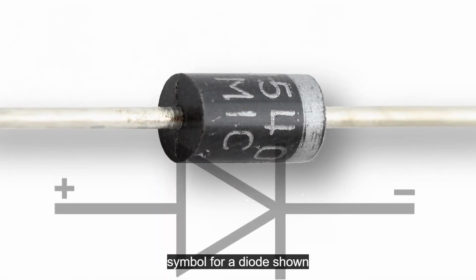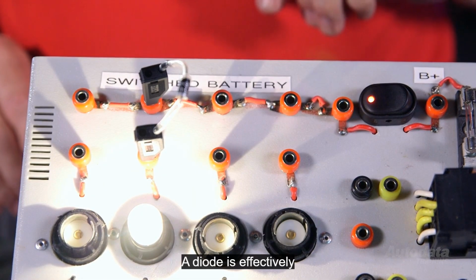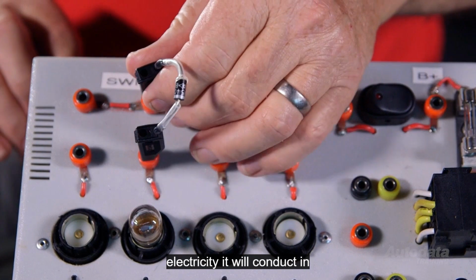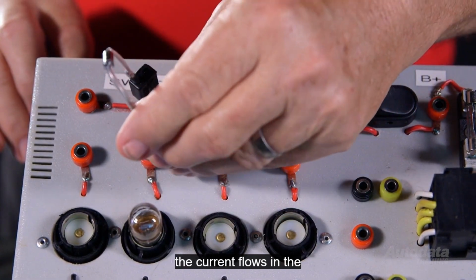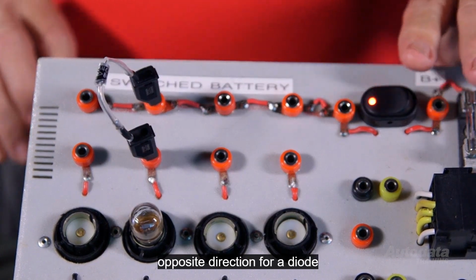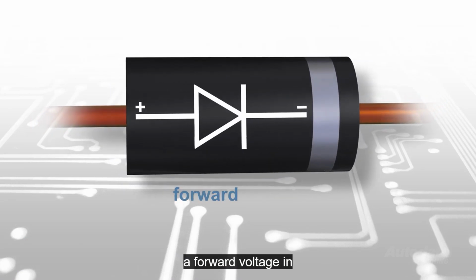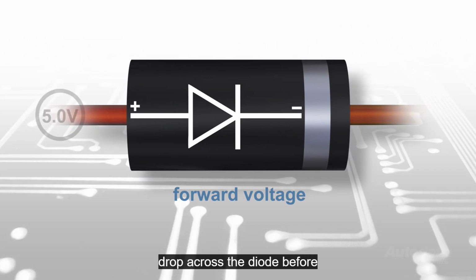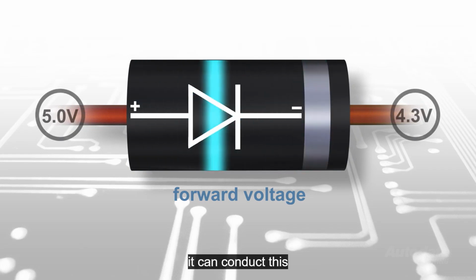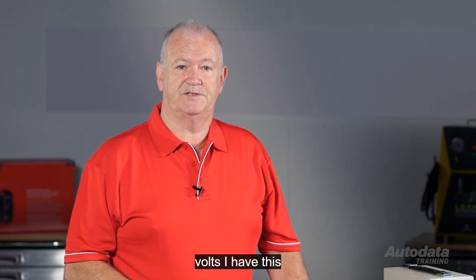This is the schematic symbol for a diode, shown next to the actual diode. A diode is effectively a one-way valve for electricity. It will conduct in one direction and insulate when the current flows in the opposite direction. For a diode to conduct, it requires a forward voltage. In other words, there must be a voltage drop across the diode before it can conduct. This is usually 0.5 to 0.8 volts.